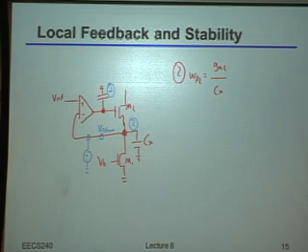Indeed, this should basically be at the FT of the device. Or at least close to it, I should say. Well, if that's the case, then where do you think you're going to want to put the dominant pole? In other words, are you going to want to make number 2 the dominant pole, or number 1 the dominant pole? Because remember, we've got a feedback loop, so we have to place the dominant pole somewhere. Who thinks they want to put it at number 2? Number 1?